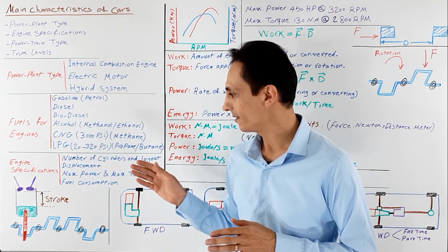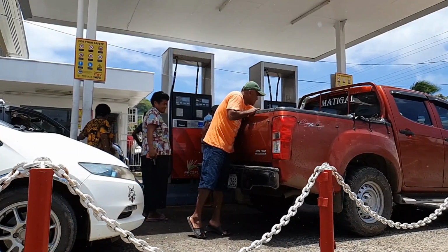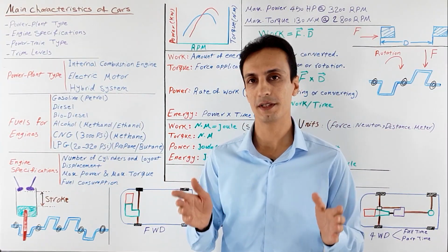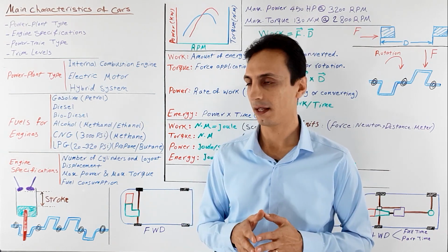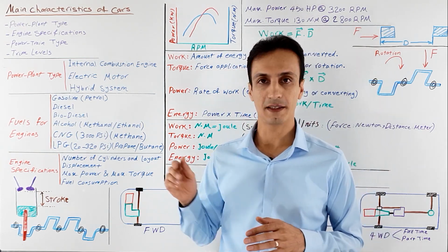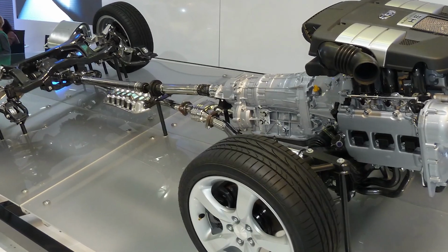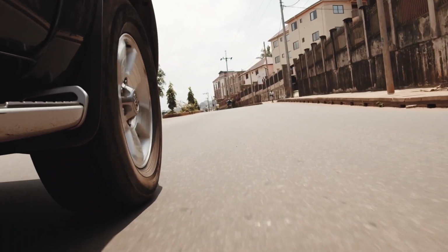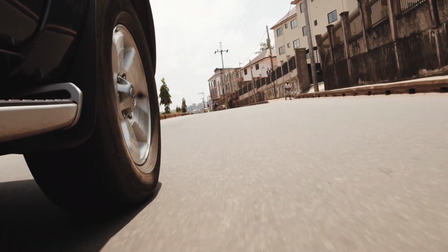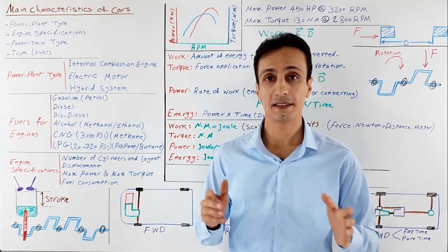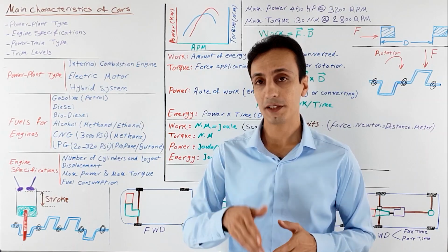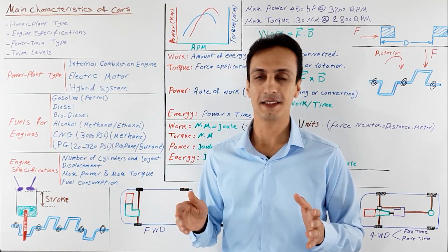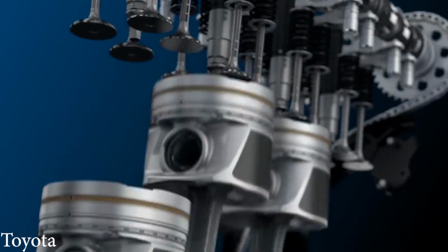Maybe I can say that this parameter is the most important thing in lower and middle class cars, and all parties have concerns about that: producer, consumer, and government. Many features of a car can affect these parameters, like efficiency of powertrain, aerodynamic drag, weight of the car, rolling resistance and inflation pressure of tires, efficiency of suspension system, and even accessories like air conditioning system, and even your driving habits can affect fuel consumption. But the most important thing in this field is efficiency of power plant or engine.